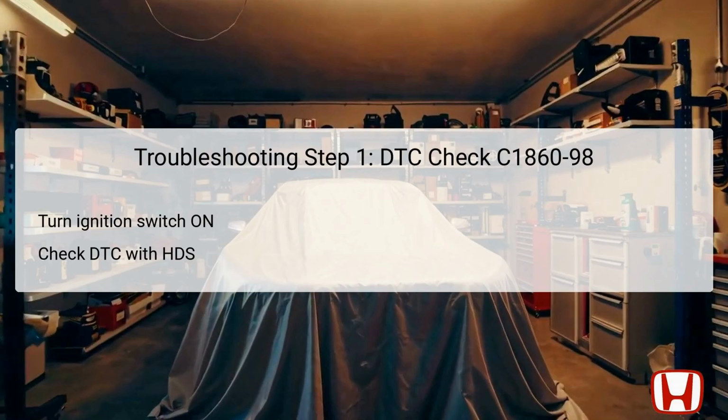The HDS tool allows technicians to retrieve and interpret any stored codes that may be present. It's essential to confirm the DTC C1860-98 is indicated to proceed. If any other DTCs are registered, they need to be evaluated. Understanding the current state of the system and any other logged DTCs is vital for effective troubleshooting.